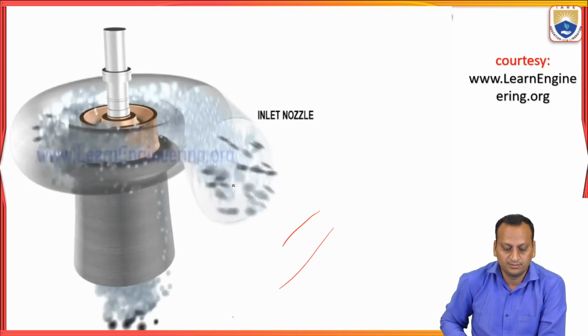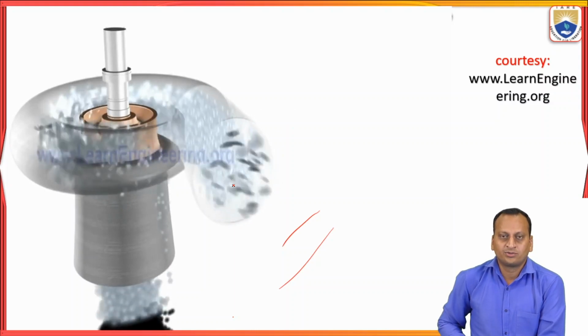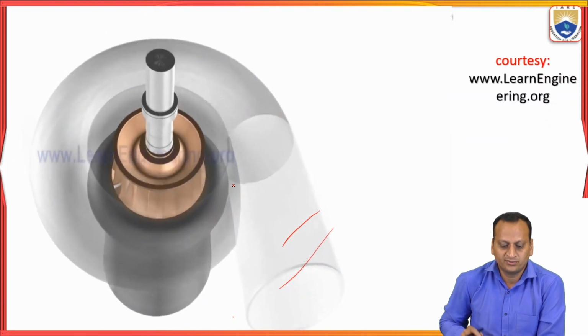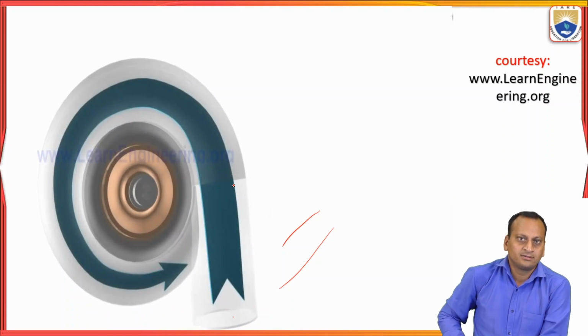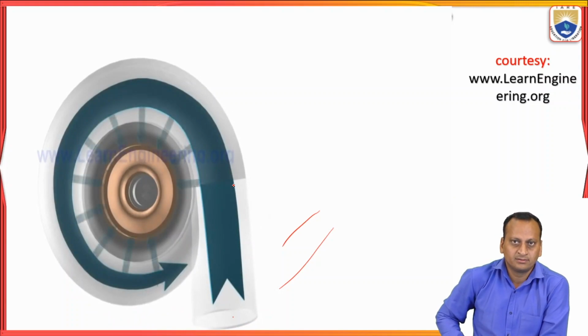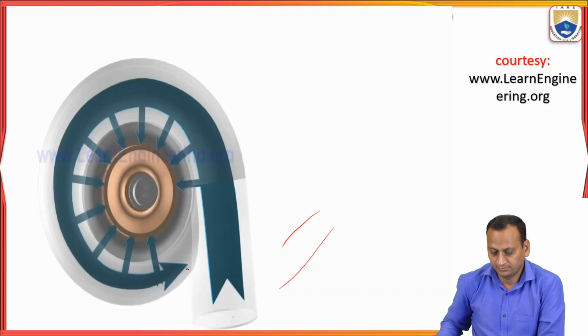Input comes from the penstock and enters the scroll casing, after which it swirls around the periphery of the rotor vane. The decreasing area of the spiral casing will make sure that flow enters the runner region at almost uniform velocity.